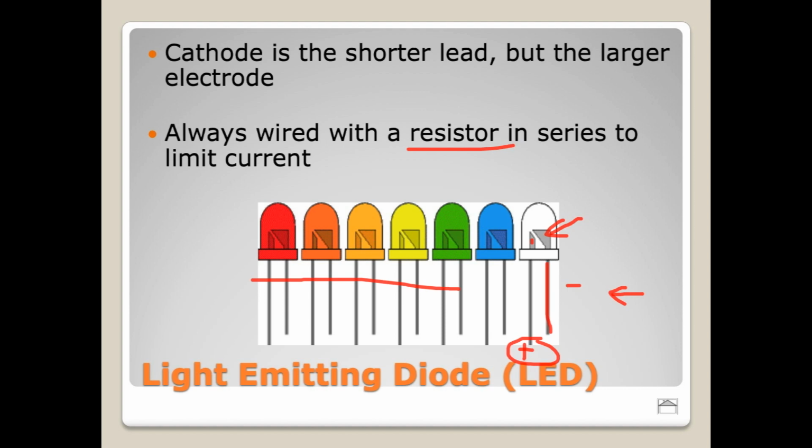Now, how much resistance? Well, that really depends on the LED. You'd have to look at some specifications. Some of them like to have something as low as 1 kilo ohm. In some other cases, I've been using resistors as high as 22 kiloohms or even 40 kiloohms. It really depends. In general, the higher you go, of course, the lower the current. You'll also find there's a voltage drop, so you will see a slightly dimmer LED as part of that process. Eventually, if you keep going up and up in resistance, you go so dim that the LED is no longer lit. So there's obviously a limit to being able to do that.